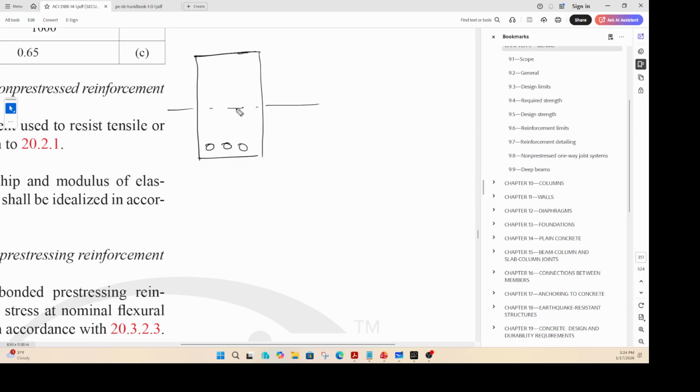So this particular zone here is subject neither to compression nor tension. Okay, now this is the geometry. Here is how the actual stress block looks, right? Stress in steel is pretty straightforward. Ast, area of steel, times yield strength. You are assuming that steel has yielded, so times yield strength. That is your tensile force.